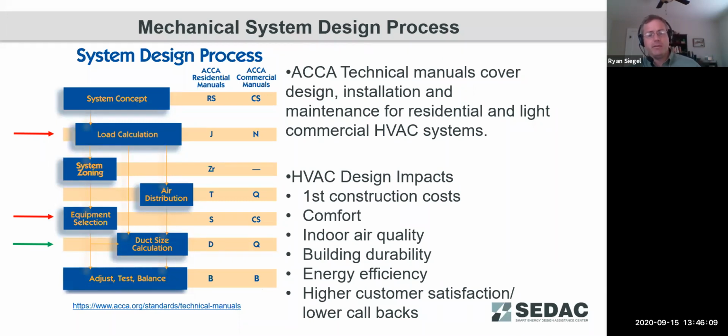Something else that can be very beneficial is that it can help drive down our first costs. Because we are building better buildings over time, with these load calcs we're seeing smaller and smaller equipment over time. One such building that we looked at, first someone came out and looked at it and said, okay, well, X number of square feet, yeah, that's going to take a 5-ton unit. Where's the load calc? Oh, well, it's so many square feet per ton.